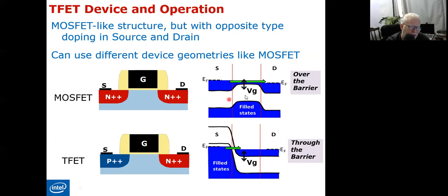So it's an NPN energy band diagram, as you can see. Okay, but now, what if I keep the gate as it is, but turn the polarity, or the doping, I mean, of one of the source and drain? So for example, here, the source is turned to be P, while the drain is kept as N. And then the substrate will be turned to be intrinsic.